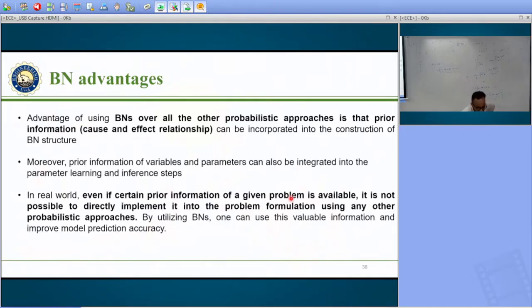So one basic thing is, in the regression part you are not introducing any structural relation, cause and effect relation between them. You are just having input and output. Initially you find the correlation analysis and then fit the model. But if you have some flow information from the process or a process flow diagram, you can bring that information into the network structure. So that is one major advantage of the Bayesian network part.